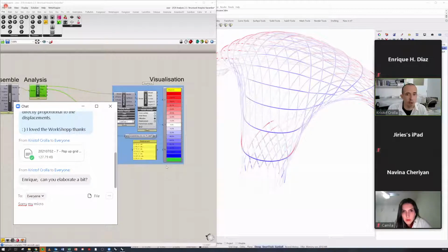From my understanding, Karamba has difficulties with calculating cables. It's a rod-based system, which is a pity, because in principle it just means that if an element is under compression, it would need to be removed from the equation. I don't know if Karamba has updated that in the past year, since the last time we spoke with them about this.